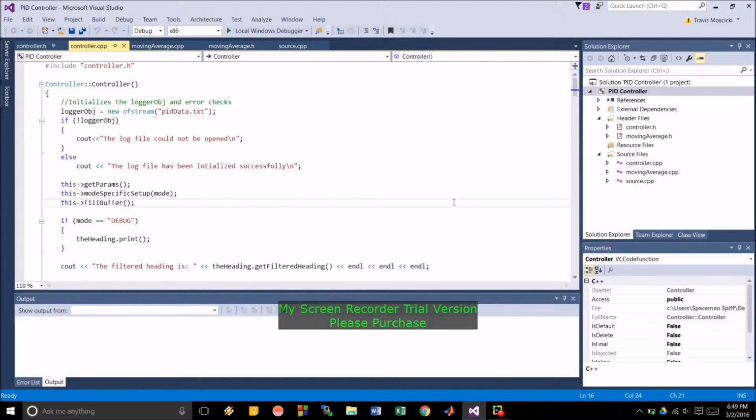Well, then you want to go with a PID because you're going to reduce that overshoot. And a PI is somewhere in between. It's got pretty good lead time, it's got pretty good overshoot, and most importantly, the steady state error is going to go to zero. So now one more quick thing about this, because this is going to come into play when you actually go about implementing a PID controller.